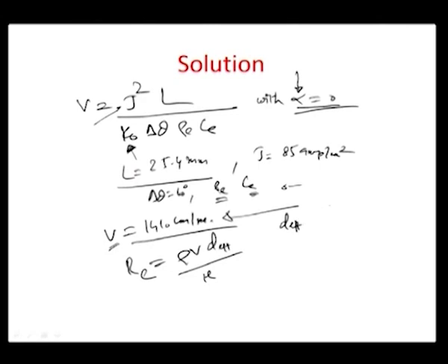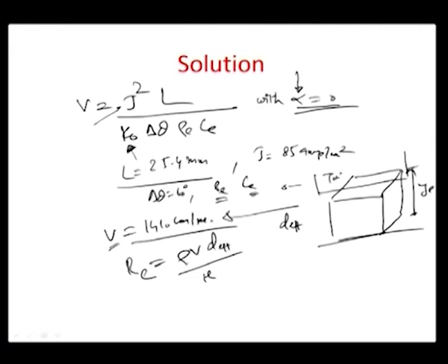This effective diameter can be calculated by looking at this cross section here. I would just like to draw your attention in the electrochemical machining process. So, this is YE, the equilibrium gap between the tool face and the workpiece. And as we already tried to analyze, this was a dx length across which the temperature was rising by d theta, and this length was assumed to be L into the plane of the paper. So, if we assume this L to be insignificant,